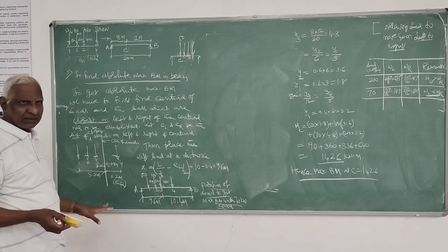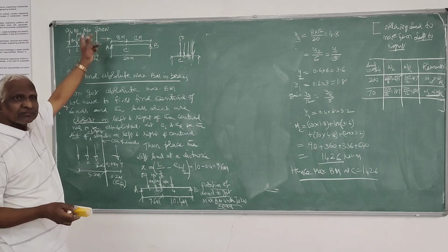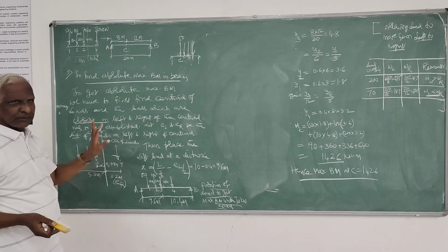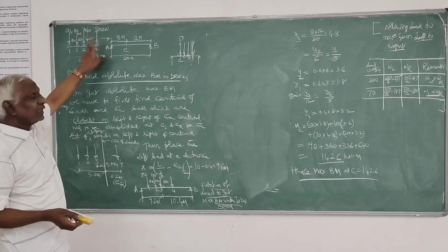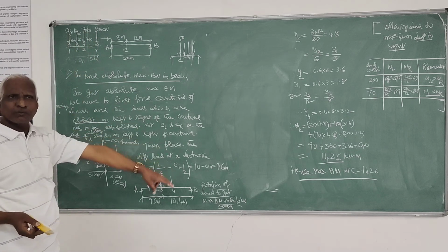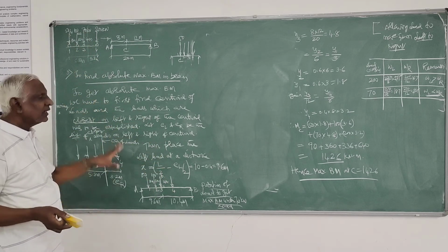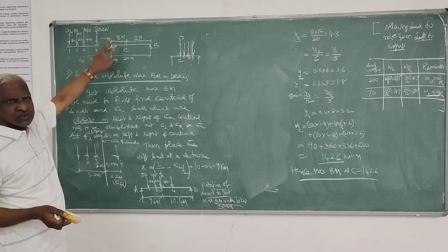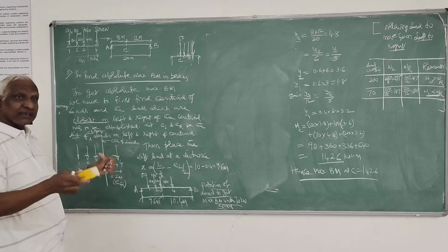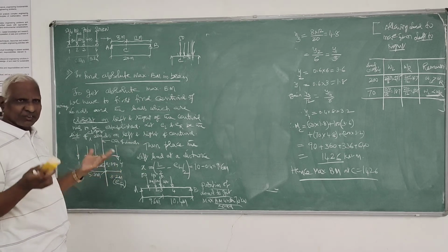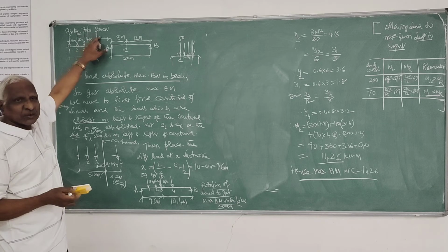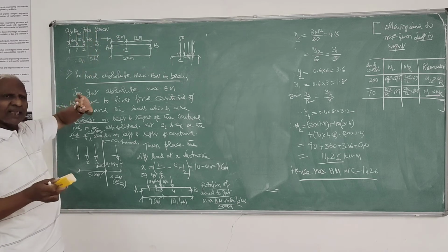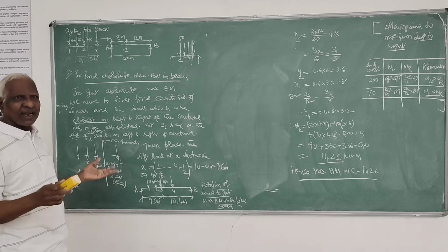You select that. Or if the difference is not much, if they are equal, then the nearest wheel load you can take and do that. Suppose both are 70, 70, then this is nearer, so only one calculation will do. Otherwise, when there is a difference between the two loads which are closer to the centroid, if you feel it is too much, here I feel it is too much because this is almost more than 50%. So that is why I will examine both the things and do that.